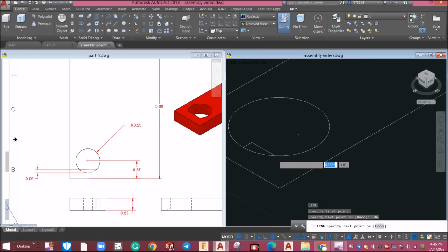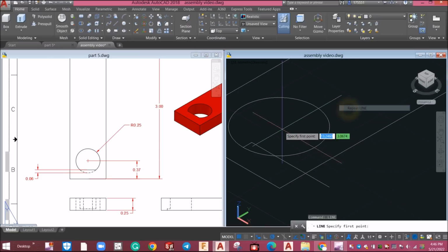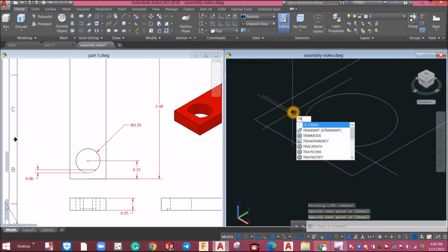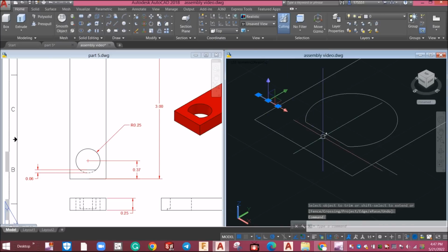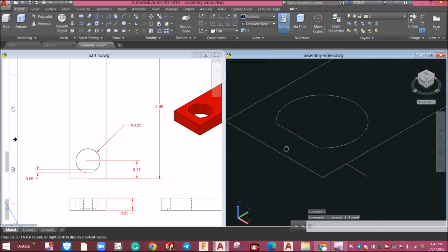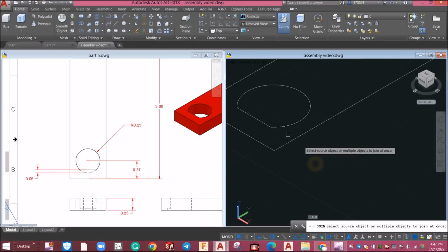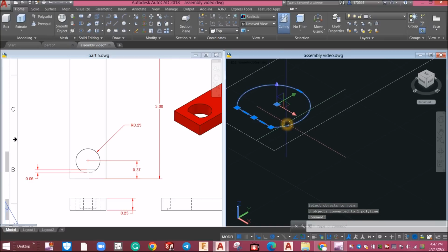So I'm going to start my cutting line from there. I could bring it here. Draw another line from this point to that point. And just trim. So TR for trim command, enter twice. Just remove that. Remove this one, remove that. Delete these two. Now I'm gonna delete that too. Join the segments. So J, join command. Select that. Now this is one object.